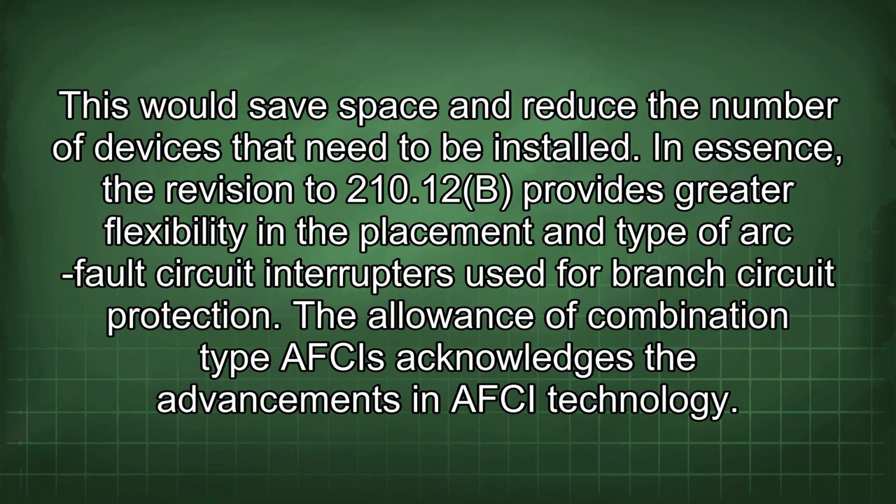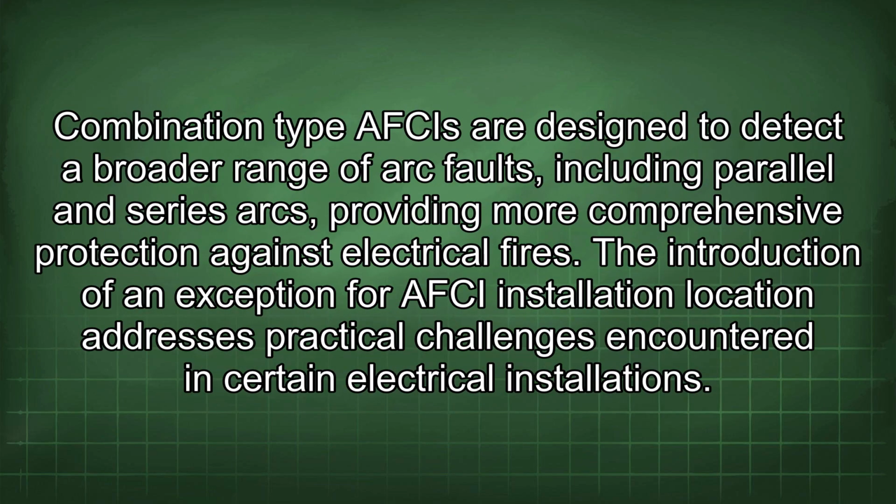In essence, the revision to 210.12(B) provides greater flexibility in the placement and type of arc fault circuit interrupters used for branch circuit protection. The allowance of combination type AFCIs acknowledges the advancements in AFCI technology. Combination type AFCIs are designed to detect a broader range of arc faults, including parallel and series arcs, providing more comprehensive protection against electrical fires.